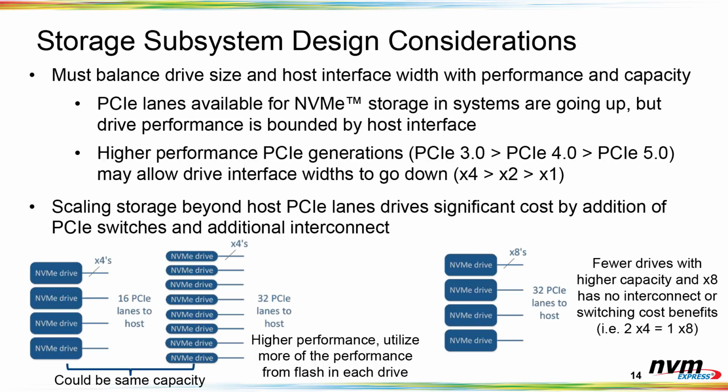And the main reason for that is there's a lot of cost from the interconnect, both in just the cabling or the connections, and then also the switching. And so for flash, there's a certain amount of bandwidth you get out of the number of channels that you have, the 8 placements or whatever of packages of NAND. With those channels, the only way usually to increase performance significantly is to start raising power. And so we're already in system, as one consideration, really hitting that bottleneck as power is the thermal design. And so that's part of the reason that you've also seen these different form factors starting to come about.